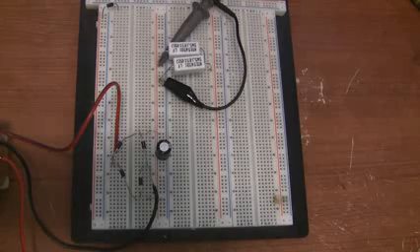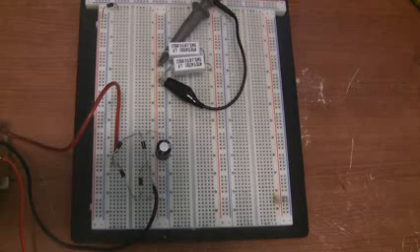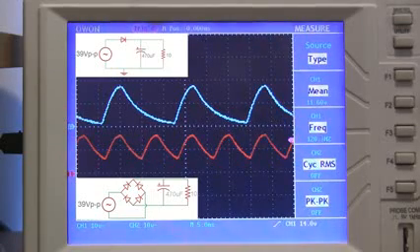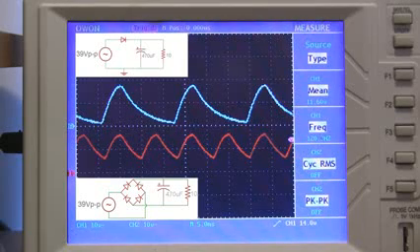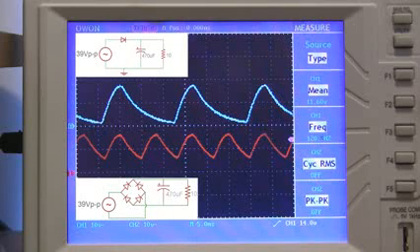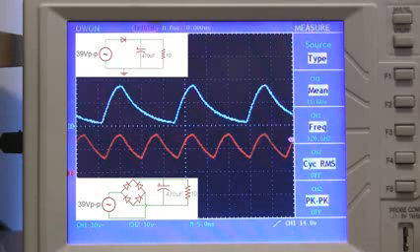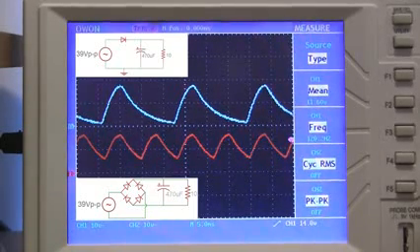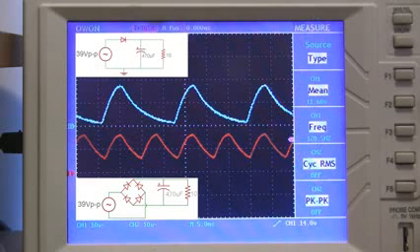This is called full wave rectification because we're rectifying the full AC wave. Now let's go back to our breadboard with a 10 ohm load and see how the bridge rectifier performs with 470 microfarads of capacitance compared to the single diode solution that we made earlier. Now we get an average of 11.6 volts instead of the 8 volts we were getting earlier with a single diode. And you can see that's because the bridge rectifier is charging up the capacitor twice as often because we're using both halves of the 60 Hz mains AC cycle. Now think about how much difference that made, given that those extra diodes only cost me 3 cents. Bridge rectifiers might be a little harder to understand, but since they work so well, everybody uses them.